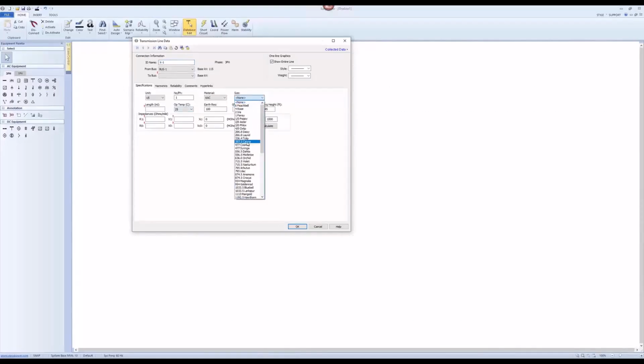Let me just choose a random number to start with, right? I will put a very short length on the gen tie line just to provide a fictitious generation interconnection tie line from the high side of my substation transformer to the utility bus, right? So, oh, EasyPower only allows 0.01. Okay, that's it.